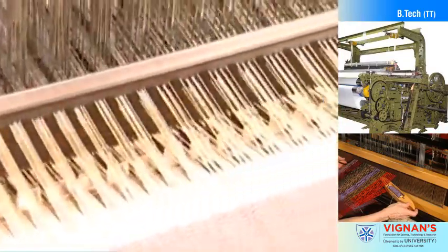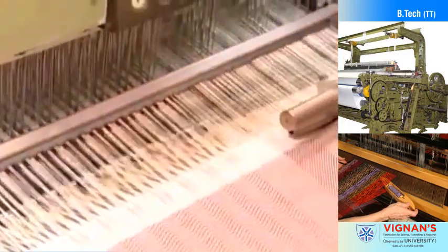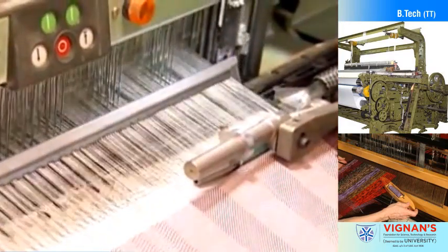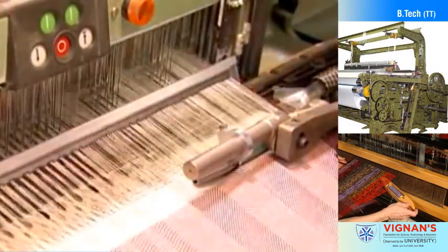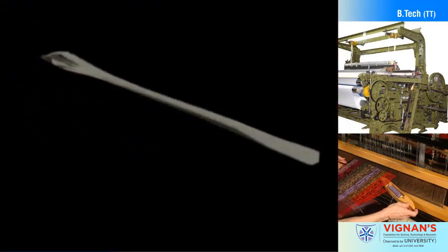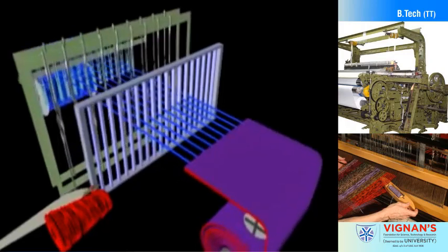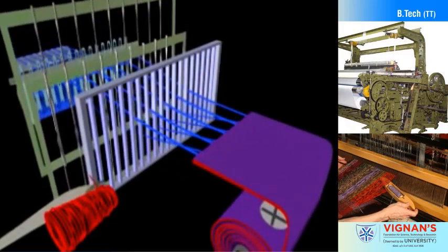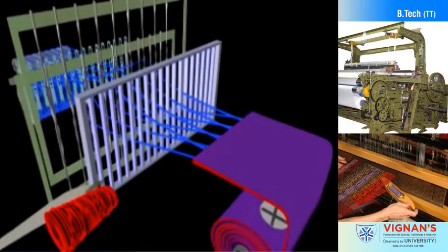There are 4 types of rapier systems: single rigid, double rigid, double flexible, and double telescoping rapiers. The single rigid rapier uses a solid rod material that carries the yarn completely across the warp. This loom footprint requires twice the floor space of the rapier due to the fact that when the rapier is not in the shed, it is housed in a sheath external to the shed.